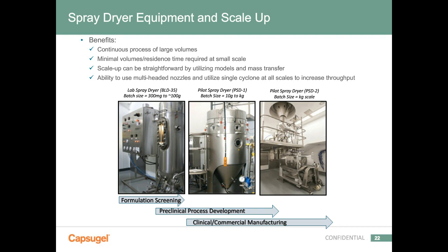And again, one thing to add is to help throughput, a lot of the times you can use multi-headed nozzles. It really depends a little bit how the material itself dries, but can be included. And then we can also utilize optimized single cyclones to help increase collection.